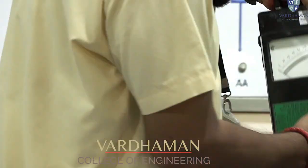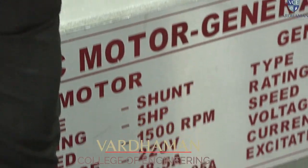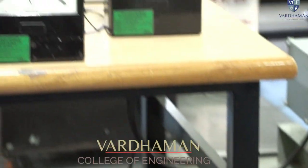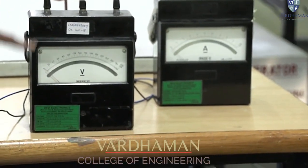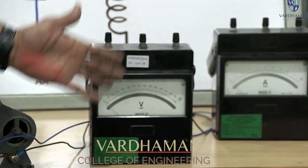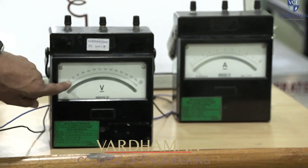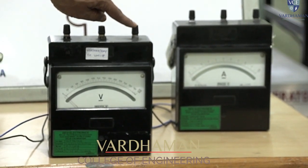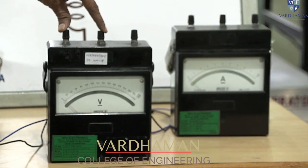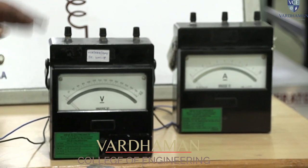So here the generator voltage is 220 volts. So the 300 volt terminal is enough for us. With the 300 volt terminal, the reading shown by the needle we can directly take as the voltage value. If you select the 600 terminal, the deflection should be multiplied by 2. So in that way, we will take the readings of the voltage. Anyhow, we are connecting to 300, so whatever the deflection is, it is the direct value, and we can note it down.